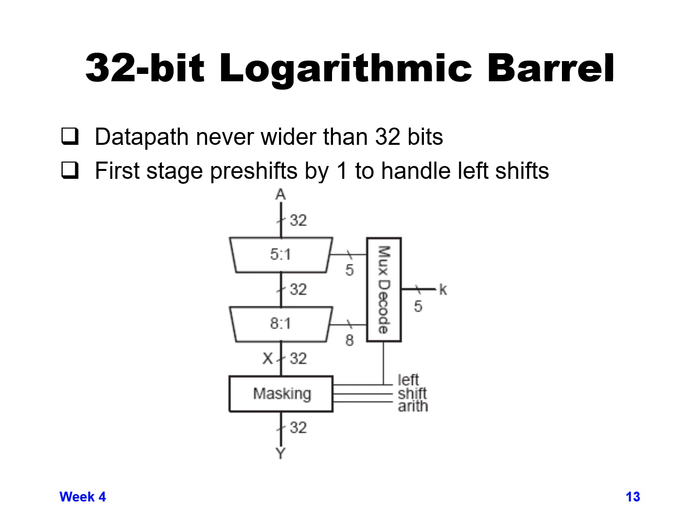So the 8-to-1 multiplexer will allow us to do either a rotate of 0, 4, 8, 12, 16, 20, 24, or 28 bits, for rotating by larger jumps of data. And so the second 8-to-1 mux will allow us to rotate up to 28 bits, and the first one allowed us to rotate up to 3 bits, which gives us up to 31 bits worth of total rotation.